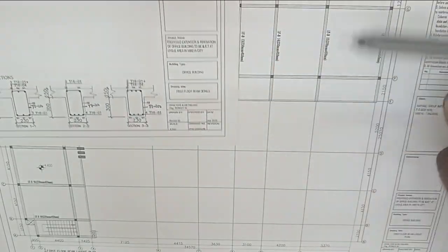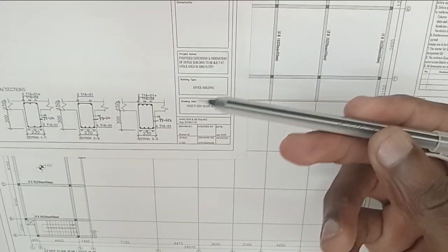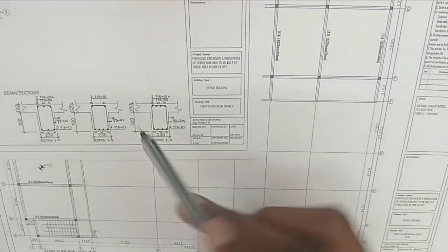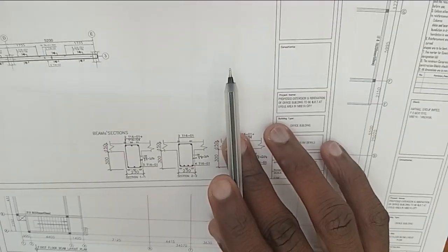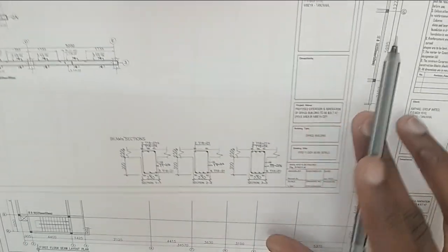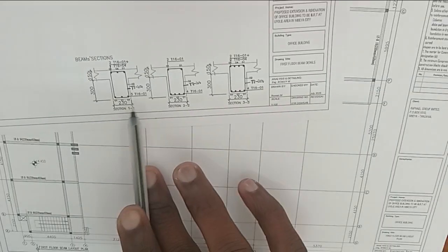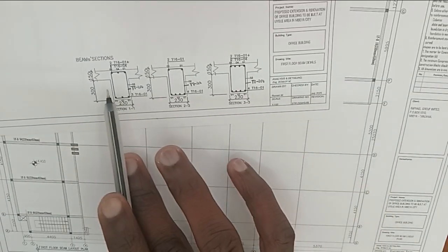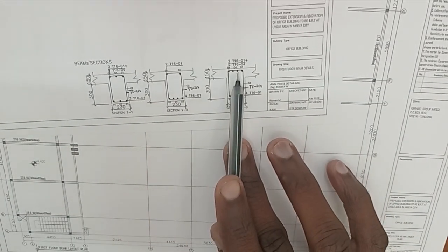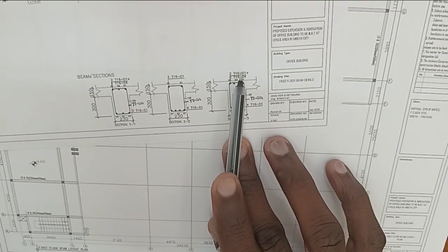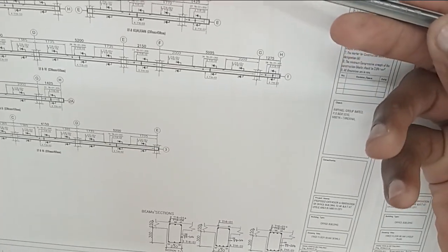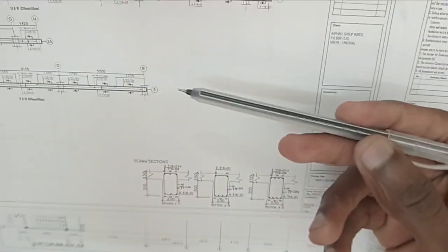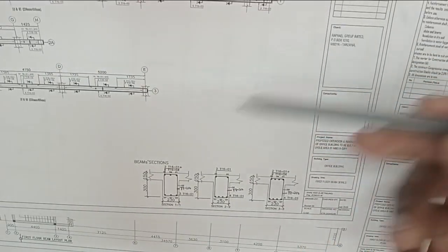So these extra bars are not provided over the whole length of the beam. Instead, they are provided only where additional strength is required. For instance, from section 1, section 2, and section 3, as we see, section 1 and section 3 have extra bars only where required. As we see in our beam elevations, these extra bars are placed over supports for negative moments.